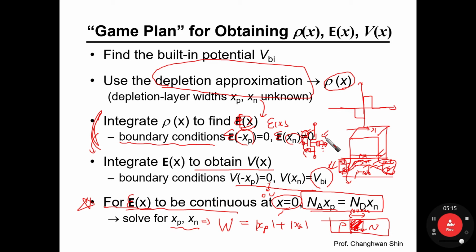How much is it? Well, it depends on the depletion layer width. So now we are almost ready to get the depletion layer below the oxide layer as well as the source and drain regions. So for this parasitic capacitance, say this is the body, C_SB, C_DB, those will be estimated quantitatively.